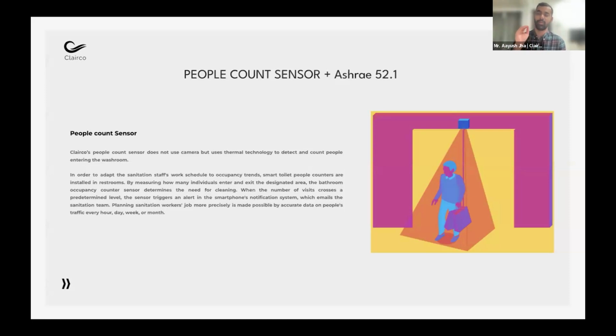This is where we'll be able to differentiate ourselves substantially in terms of bringing the wellness to the next level, which is at the moment not happening in the way which I anticipate how the buildings should work. What is happening right now, we have demand-based ventilation, where when the carbon dioxide levels achieve, say 1,000 ppm or a 1,200 ppm or a 950 ppm is when they usually kick off. This is a reactive technology.